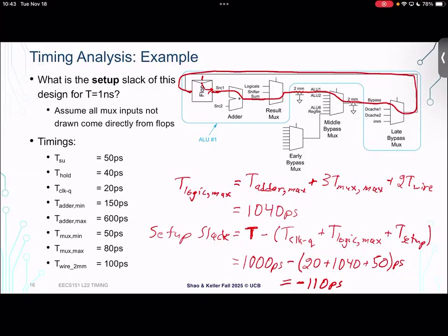For a combinational gate, the difference tends to be not that large. For a multi-bit circuit, like an adder, for example, the min versus max delay can be quite large, as is shown in this example. Because for our adder, we were always looking at what's the slowest delay to that last bit, bit 31, typically, to calculate the very last one, right? And that set our worst case delay. But data could start to change much more quickly in bit 0. So you have this case where the fast bits, quote unquote, of the adder can be toggling way, way before the slowest delay through the adder.